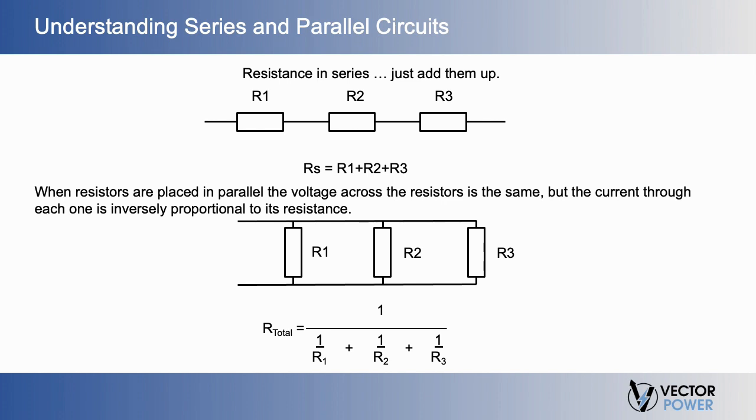Another area that can be confusing is that insulation resistance measurements are typically line to ground measurements. Therefore, understanding series and parallel circuits is essential when evaluating test results.